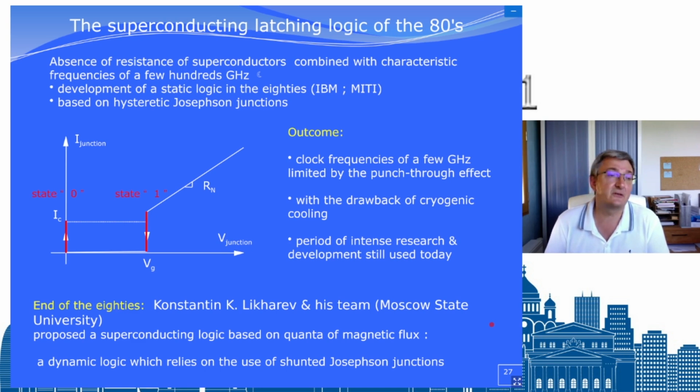It was mostly lead technology, with lead as the superconductor. And the problem with this material is that when you cool it, it becomes superconducting, but when you make a thermal cycle, you stop it and you cool it again, the junction had different properties. It was not stable at all for physical-chemistry reasons. And then it was like really jewelry and very complicated to get this working. But it worked up to a few gigahertz.